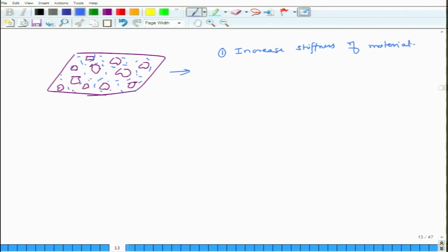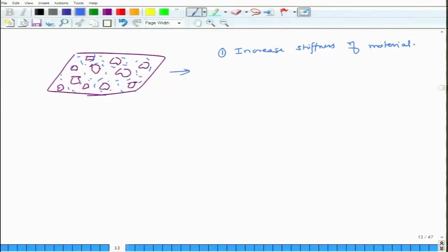For instance, if you take a slab of cement and put some compressive load on it, it will have some stiffness, but if you have a concrete, if you mix it with lot of these pebbles and particles, then it becomes significantly stiffer. So, it can take much higher compressive loads. Okay. So, a lot of times if we have to increase the stiffness of the material, we mix them with some particles, okay, and these particles should be stiffer than the matrix material, then only it will increase the stiffness.